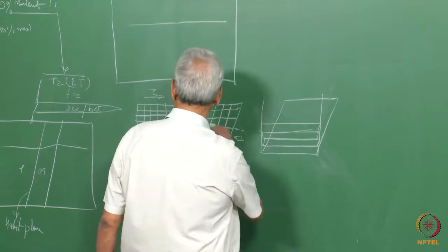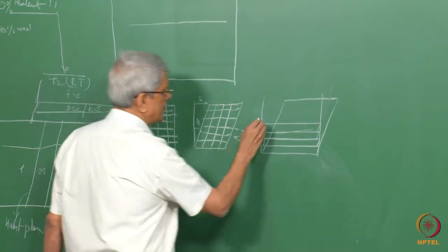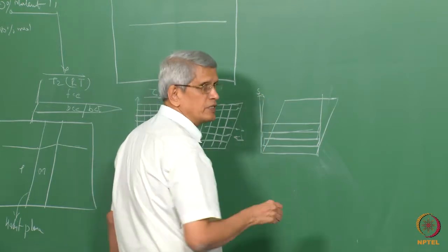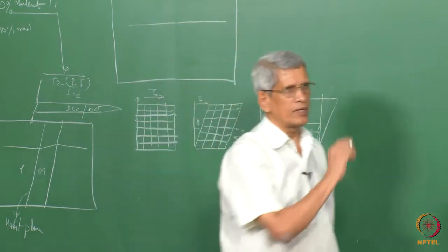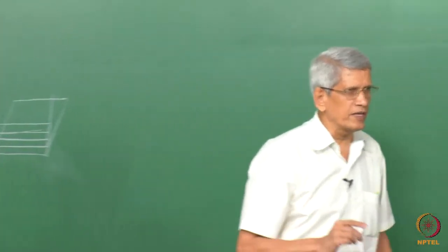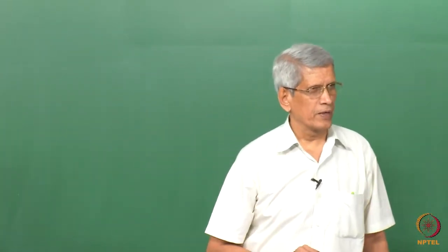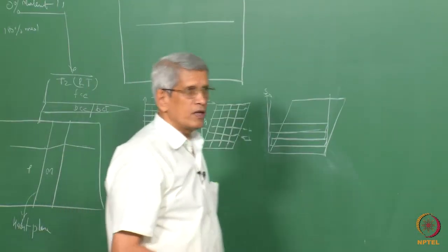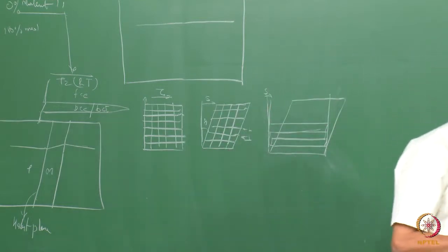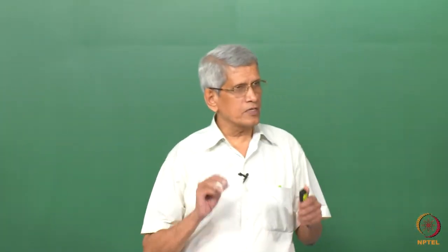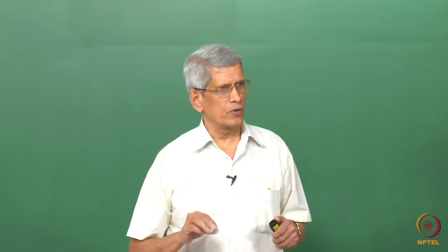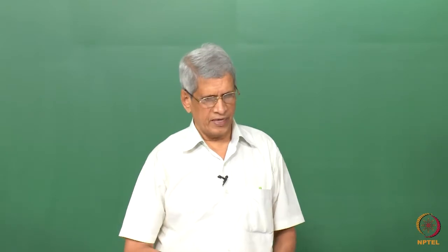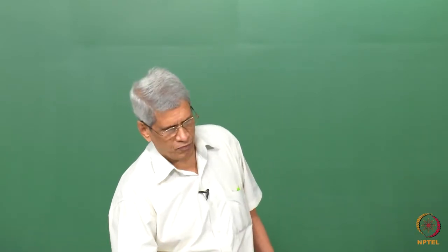Now if we look with respect to this direction, the shape strain is very small. This is the observable strain which we see during the martensitic transformation. Does this structure correspond to just a simple homogeneous shear? No. A homogeneous shear has transformed it, and then we have introduced the lattice invariant shear.